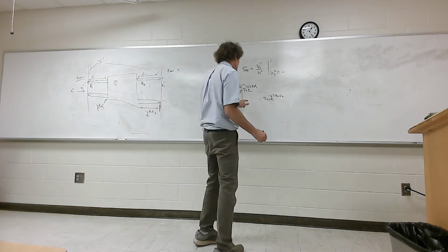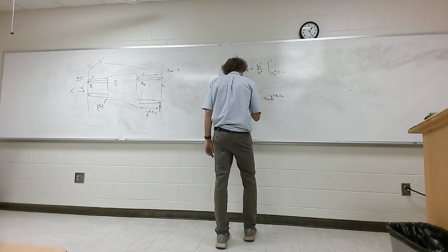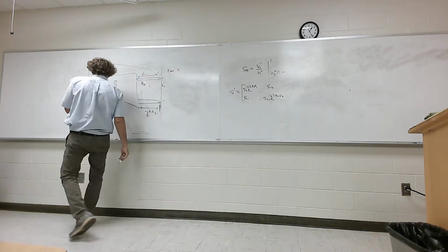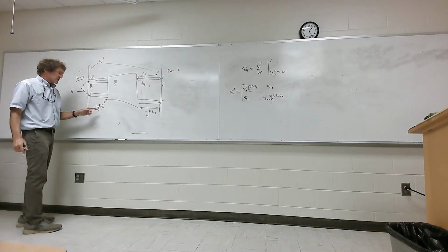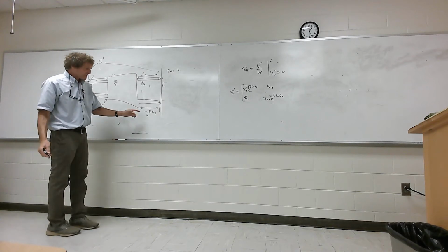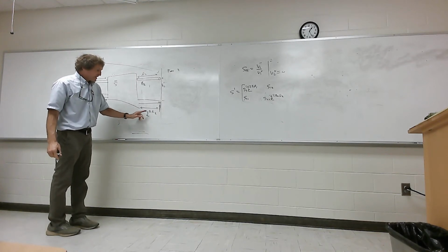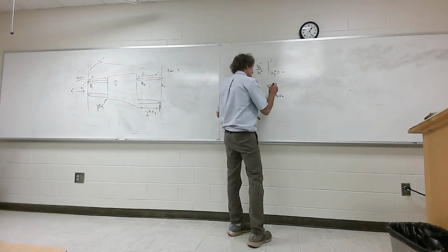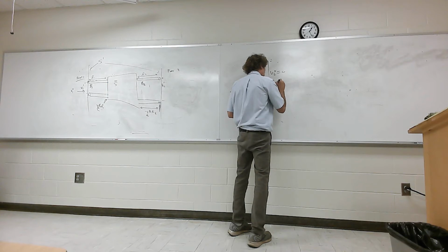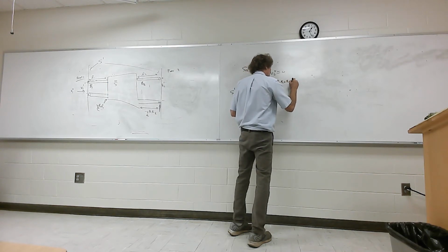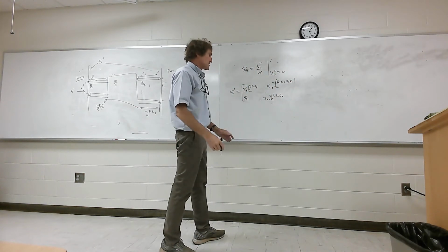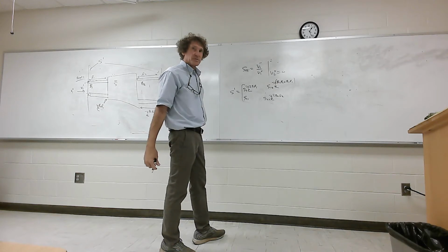So now these two here, S21 and S12, are going to be affected, and the phase change from here to here would be e to the minus j beta 1 L1 plus e to the minus j beta 2 L2, or really it would be e to the minus j times beta 2 L2 plus beta 1 L1. If beta 1 is equal to beta 2, you can just take it out in front and put e to the minus j beta times L1 plus L2.